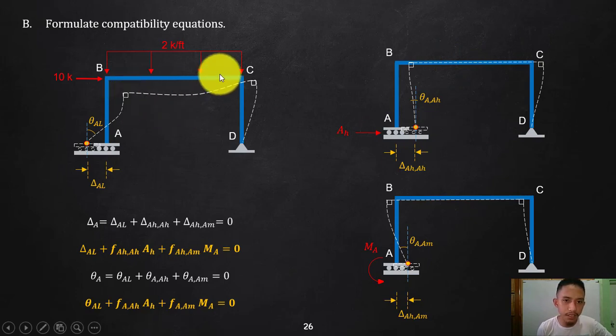By the way, what are these 90 degrees here? That is a frame. So there will be no deformation on the connection because that is a frame. It is formed to be a fixed connection. Unlike in the truss, where the connection will actually adjust since that is a pin. But in a frame that will always be the same orientation. So if that is originally 90 degrees, then that will always be 90 degrees. So again, this is the redundant AH, so that might be the deflection. Maybe that will be the rotation and deflection.